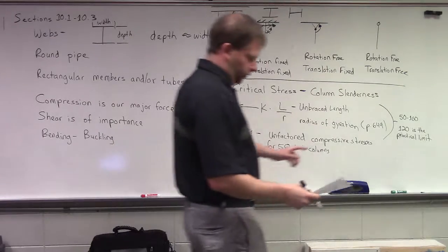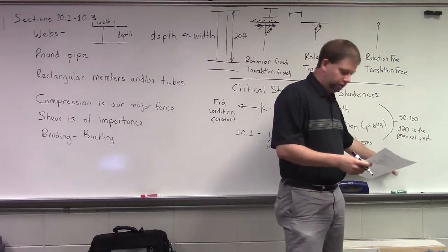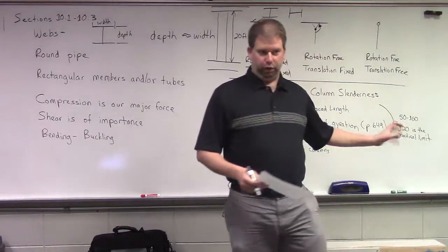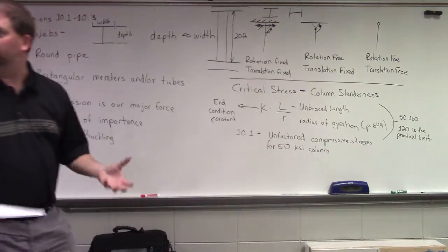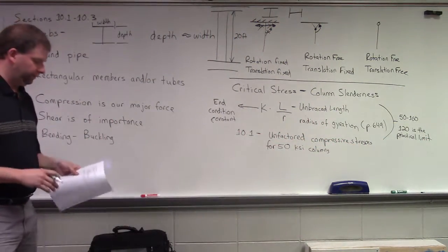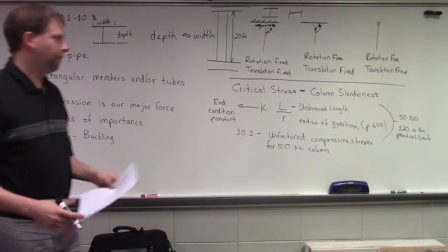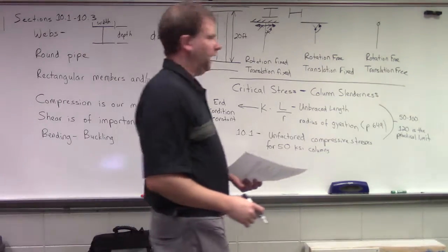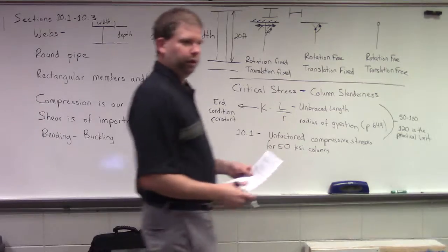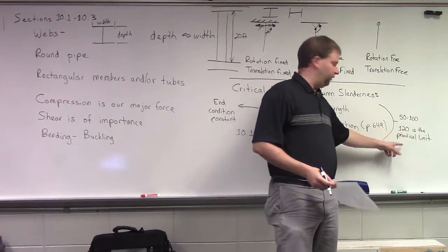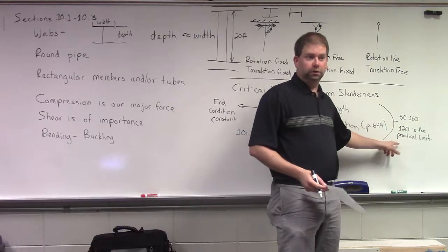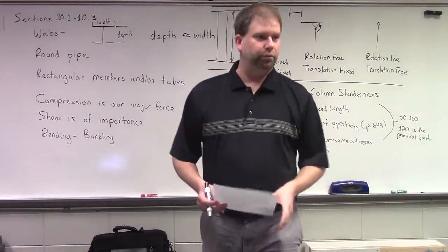If you get up close to 200, really bad things can start happening. Now you're starting to run the risk of buckling. If we pop out an answer at 105, 110, it's okay. Yeah, absolutely. I wouldn't stress if you get out of this range. If you start getting above 120 though, then we should sharpen the pencil a little bit.